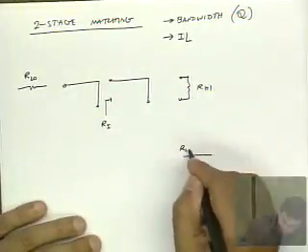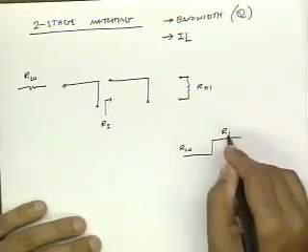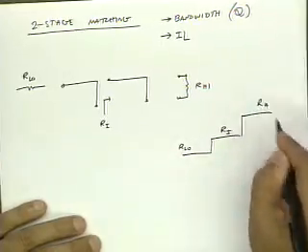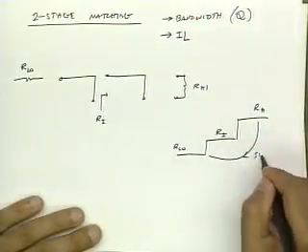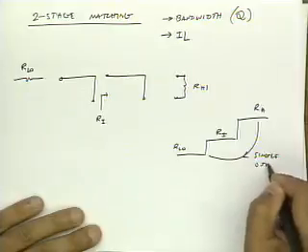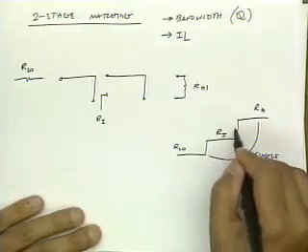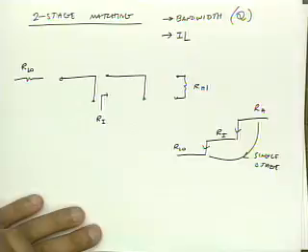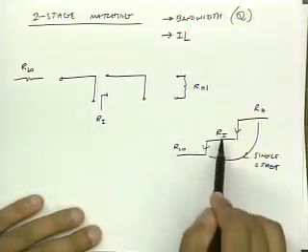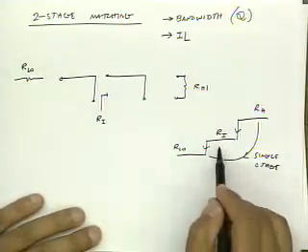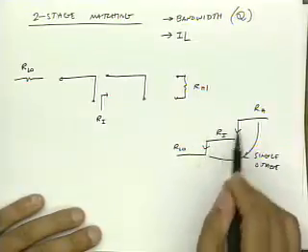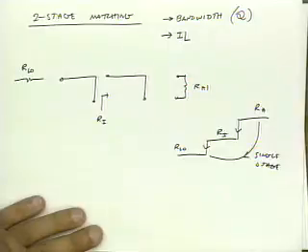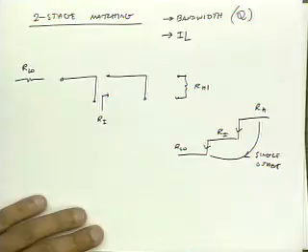So if R low is here, this is R intermediate, and this is R high. In a single matching network, I take one jump. In a two-stage matching network, I actually take two steps. And now you see that that extra degree of freedom is Ri. I can choose any intermediate Ri between R low and R high, and this circuit still works, right? So this introduces 1 degree of freedom.